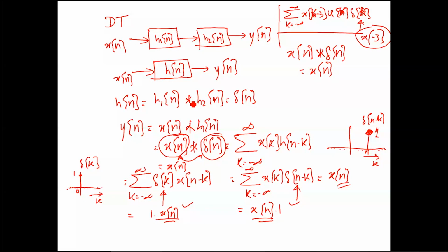Whenever you see a complex looking summation or integration where step signals and impulse signals are multiplied together, always just look for the impulse. If an impulse is there, you can directly write the answer without going into much detail. And if an impulse is not there but step signals are, step signals always just change the limit. So we plug in the appropriate limits and then solve it accordingly.